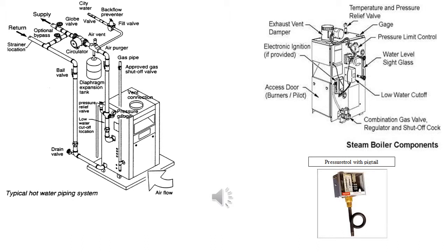If the water level is too low, the system is at risk of not operating properly. This is due to the fact that as the water turns to steam, it takes a little while for the steam to condense and return back to the boiler. It could drop the water level in the steam boiler below the minimum water level, and the burner will shut down. A forced hot water boiler does not have a gauge glass. The system is completely full of water.